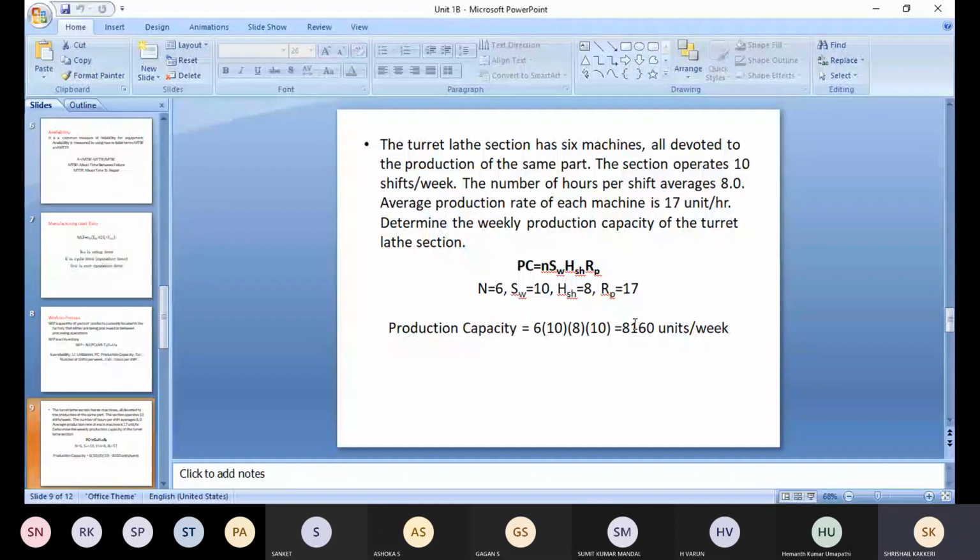In flexible automation, as the name indicates, it is flexible in nature. That means a small flexibility will be provided to change over to a limited type of productions by small changes in the machine setup, machine configurations, and some other small changes, and we can change over the production. Since we can change over the production, the varieties of product can be maximum as compared to fixed automation, and the quantity will be limited. The production quantity will be less as compared to fixed automation.